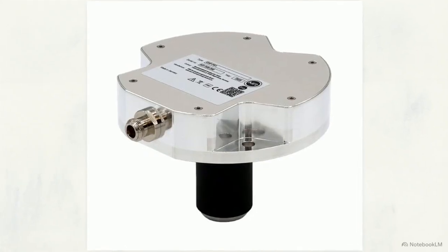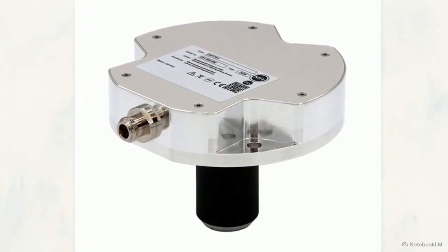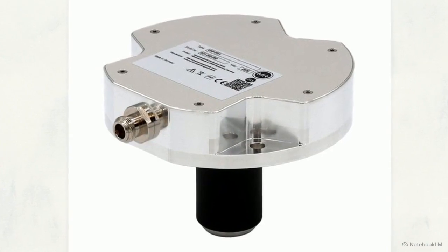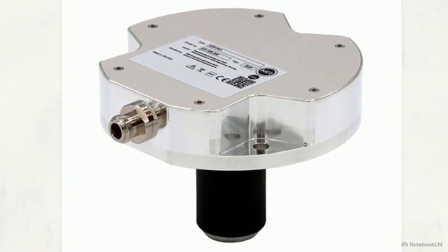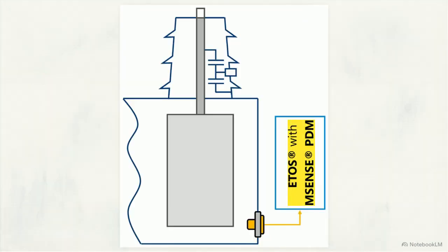Ultra-high frequency, or UHF, sensing is the primary non-conventional method. These sensors detect gigahertz range emissions, bypassing lower frequency noise generated by external corona discharges. These sensors can be deployed on live, sealed infrastructure without physical modification.